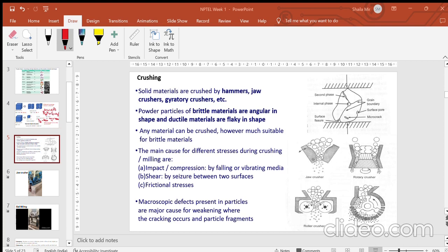A ball mill always runs at capacities lower than its full capacity. So you have to give some free space inside the ball mill while running it, right? So one important parameter in ball milling is the ratio of your feed material to the balls. Second is how many rotations you are giving to the ball mill, that means the rotations per second, or the milling speed of the ball mill. The milling speed will help you achieve the crushing of your materials, right?